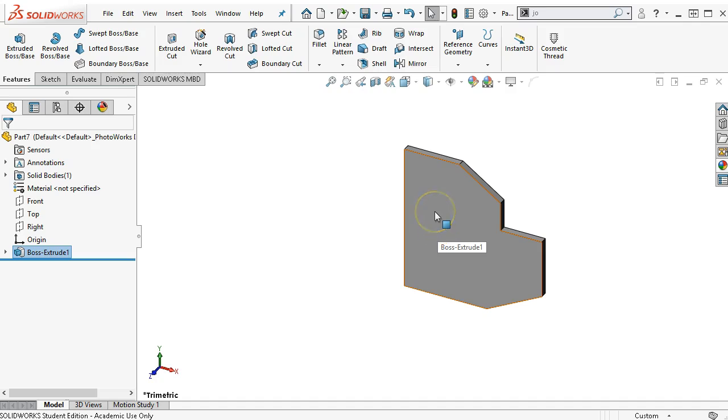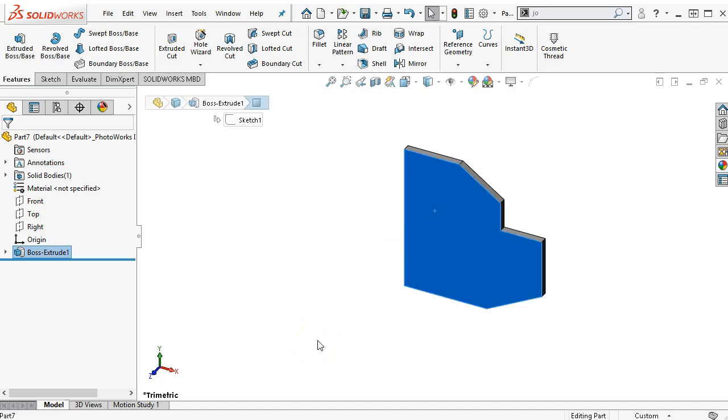Alright, so if I pre-select the face, and this would be another instance where I can use the S key, and the S key is just going to be this little pop-up menu that wherever your selection tool is at, it's going to give you those options. So I can find the extrude cut. If we do the pull-out arrow, then I'm still going to have those other options within its group.